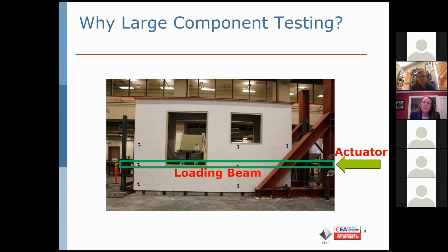And they had found that the boundary conditions of that test, in exactly the way that Tara was talking about, had a huge impact on the outcome of the test. And so particularly for stucco and other materials with continuity, we knew that boundary conditions were incredibly important and could easily maybe double the capacity and drastically change the displacement at peak capacity and beyond.